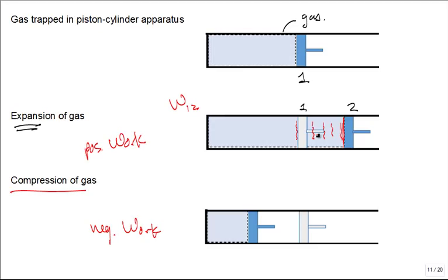The gas has more room now. So the gas pressure is probably lower. So the pressure on the face of the piston is probably lower. True? So if I made a property diagram, this is the pressure axis, not the velocity axis, volume axis, true? And I plotted pressure.